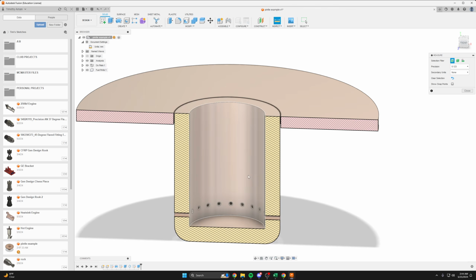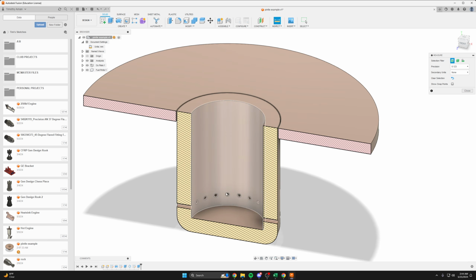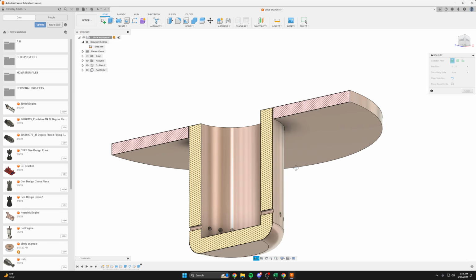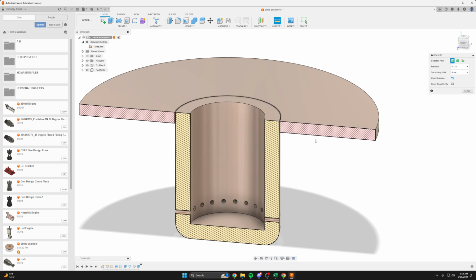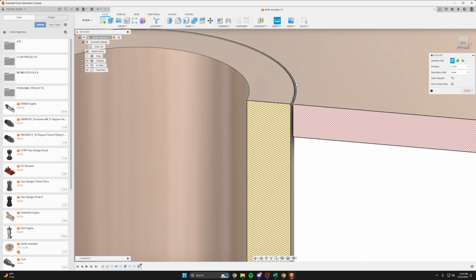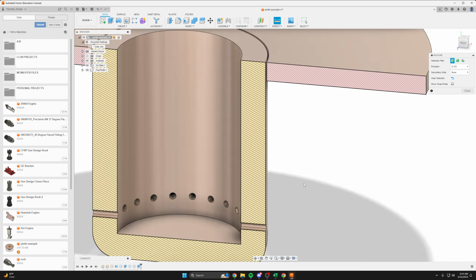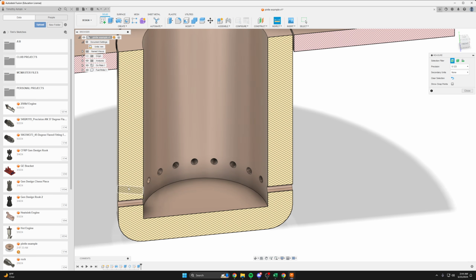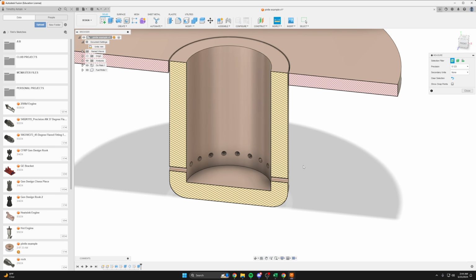You can see here's half of our 20 holes. This is the pintle post. So the fuel would come down here and go out through these holes. Obviously, this is not very realistic, but I just mocked it up real quick. And then the liquid oxygen would come through this annulus gap as a sort of sheet, and hopefully we would get some kind of mixing and atomization and combustion.